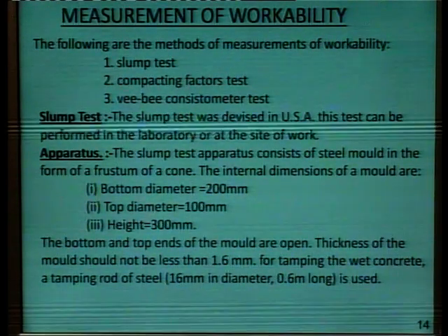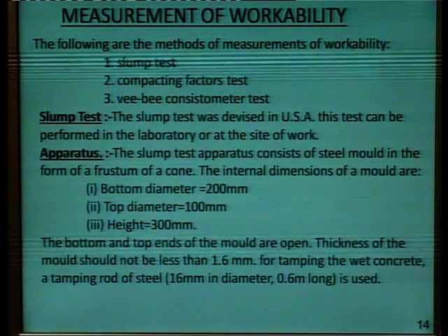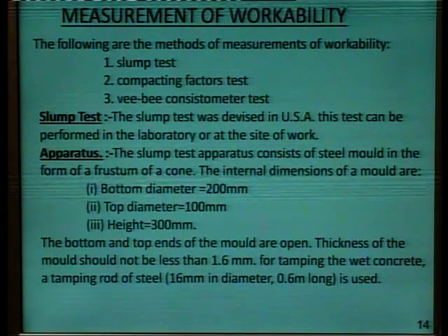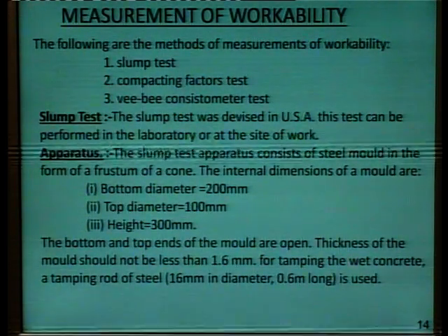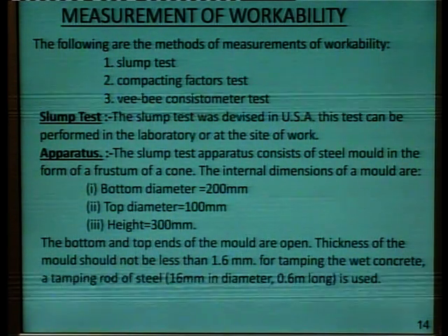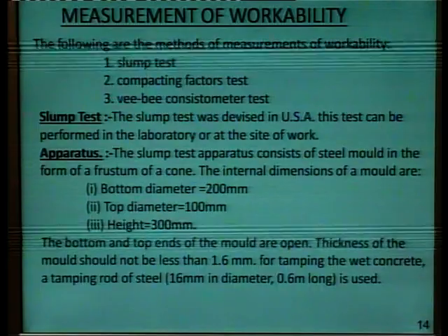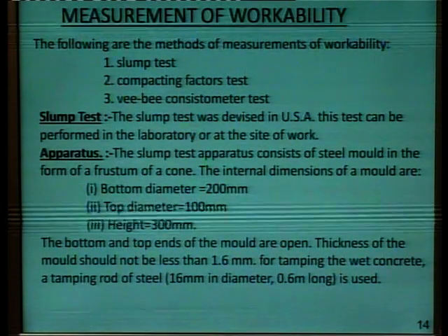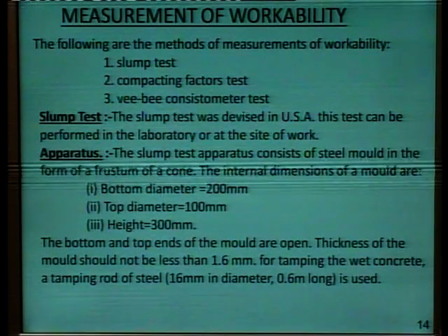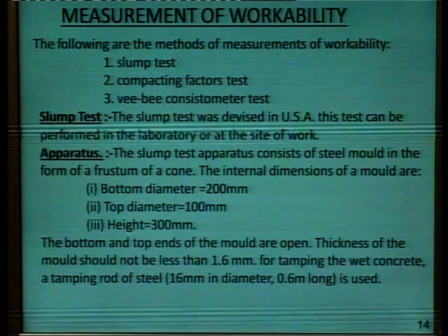These tests are, first one is slump test, second is compacting factor test, and third is VB consistometer test. So, these are the 3 tests which we perform in our field or in our laboratory to find out workability of concrete.